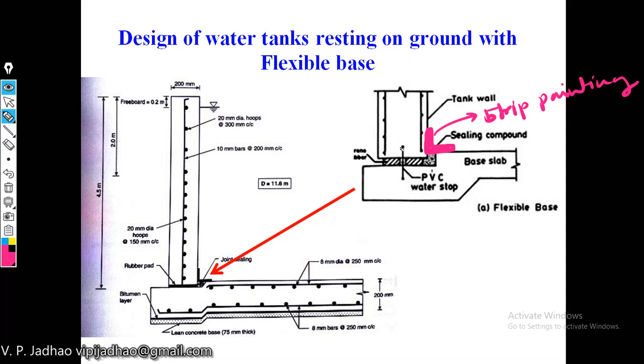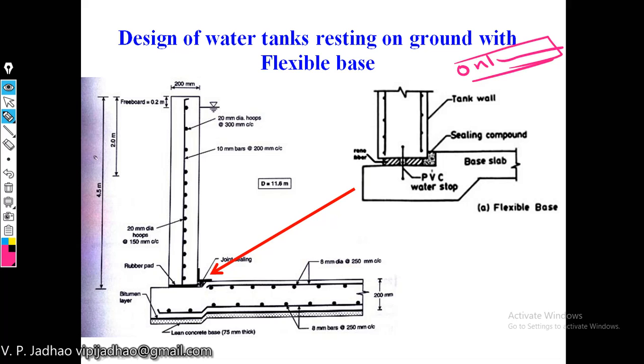Okay, due to the pressure from the water like this, this particular wall will be allowed to move away in small amount or small deformation. Due to this movement, no bending moments are developed in the wall, and only tensile forces or hoop tension will be developed.